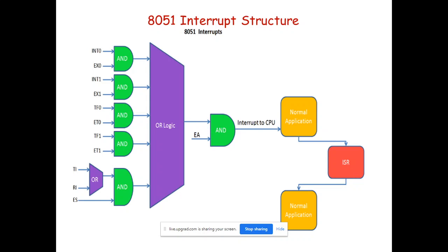from the ISR. At the end of the ISR, which type of instruction is there? RETI. When RETI comes, the controller returns to the main program by taking the return address from the stack. And for that, which instruction is it using? POP. It pops the return address as well as the dedicated data which was preserved when it jumped to the ISR. Agree with this?